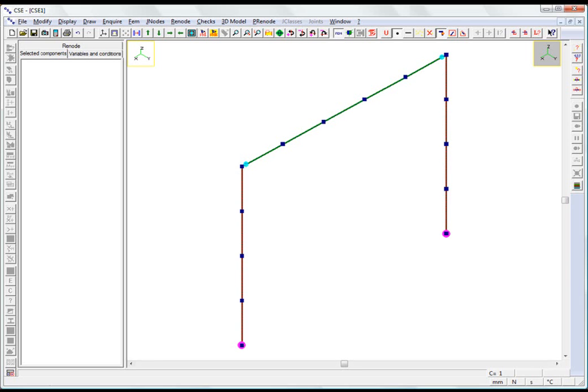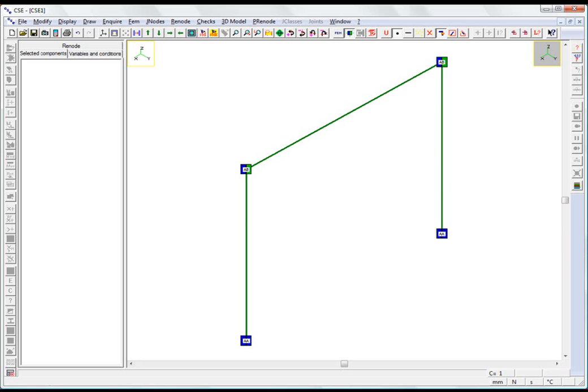The nodes in the finite element model where several members connect together and or with the reference are known as Jnodes, from joint and node. In order to distinguish Jnodes from nodes, a model of finite elements must first be converted into a model of members. A member is a physically unique entity with no internal connections. It is generally modeled using several beam-type finite elements or one truss-type finite element. By examining the model of members, we can understand which nodes are also Jnodes.